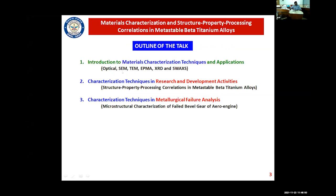As I mentioned, these are optical microscopy, scanning electron microscopy, transmission electron microscopy, and electron probe microanalyzer, which are the microstructural characterization techniques. TEM we can also use for crystal structure determination. Structural characterization techniques like crystal structure determination we can do using X-ray diffraction and the small and wide angle X-ray scattering techniques.